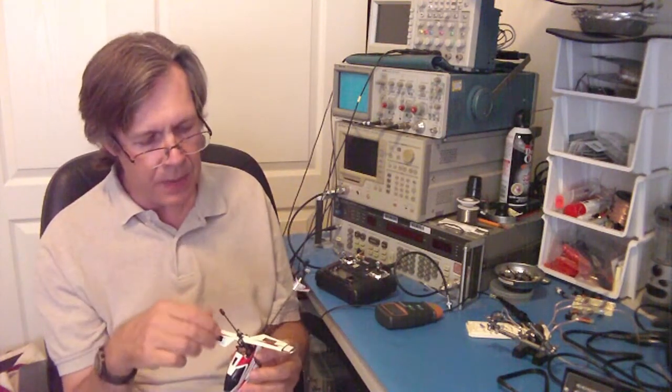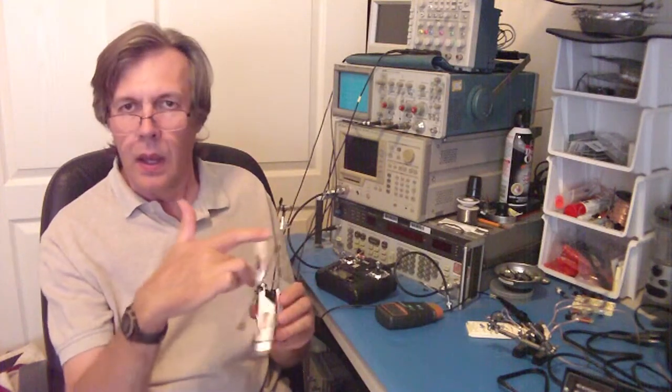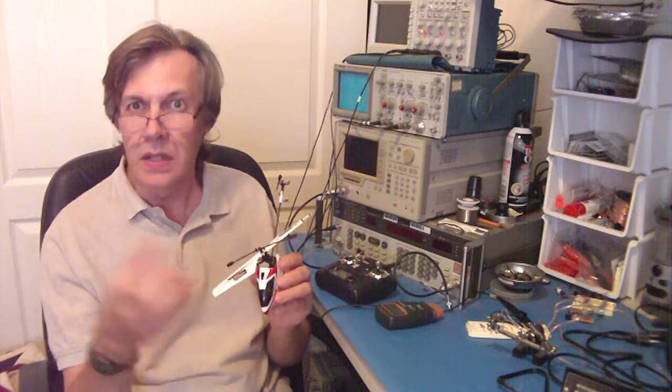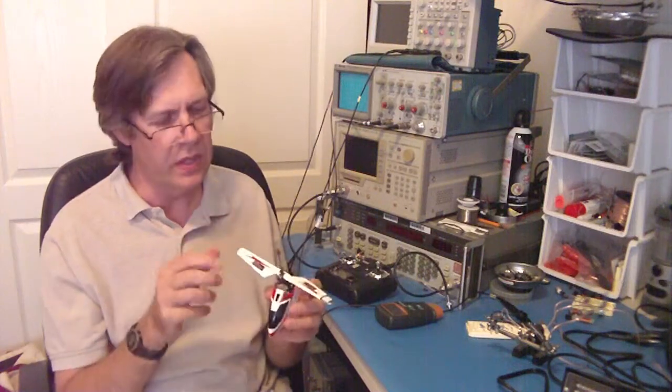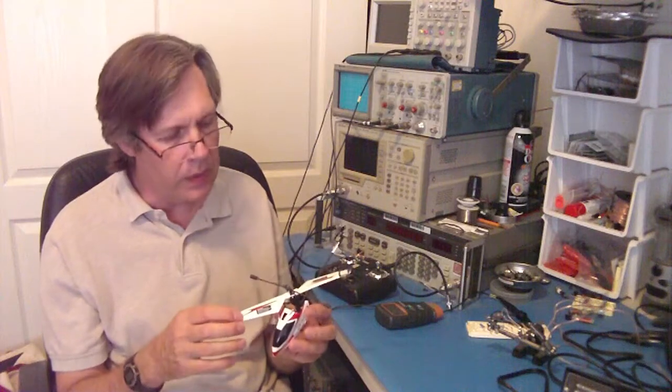Because what happens in a sampled system is as the blade's turning and you're taking snapshots of it, you only see the blade in certain positions because it's in discrete time now. Like in the movie, we're taking only frames of it in particular positions, and that's why you see it maybe turning backwards or something like that, or propeller or wagon wheels.